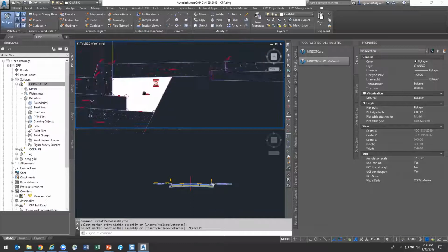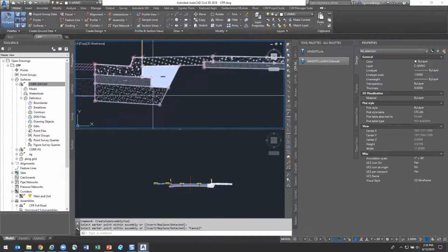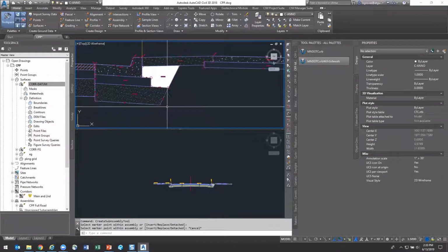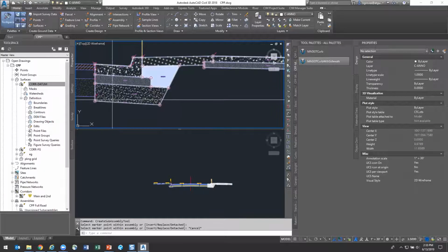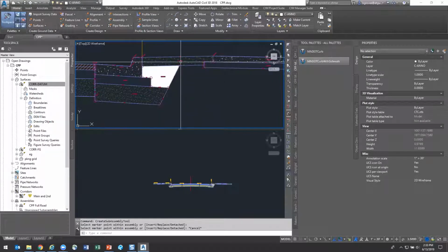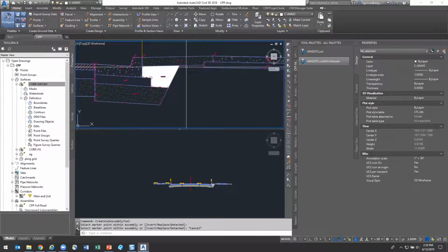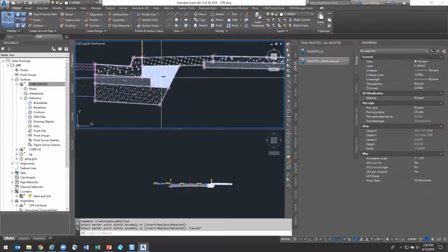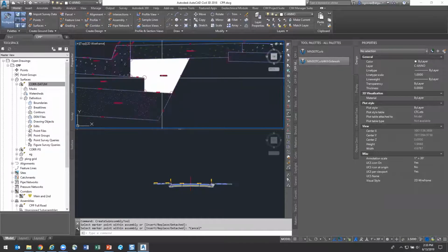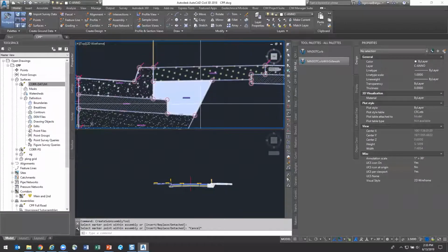And that's the common area. So when I go through and I build this in the real world, yes, I have to excavate down for my base and then I have to come up. But I'm gonna put in my base, I'm gonna put in my sub base, and I'm gonna put in my curb and my topsoil on top and so on and so forth. But this is material that has to get put back in, and it's really easy to miss this, and it's kind of tough to define as part of your quantification for your project without having this shape in here.